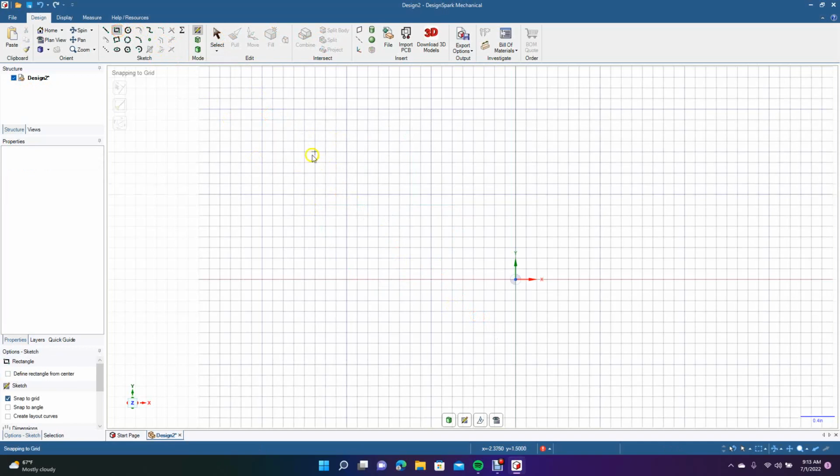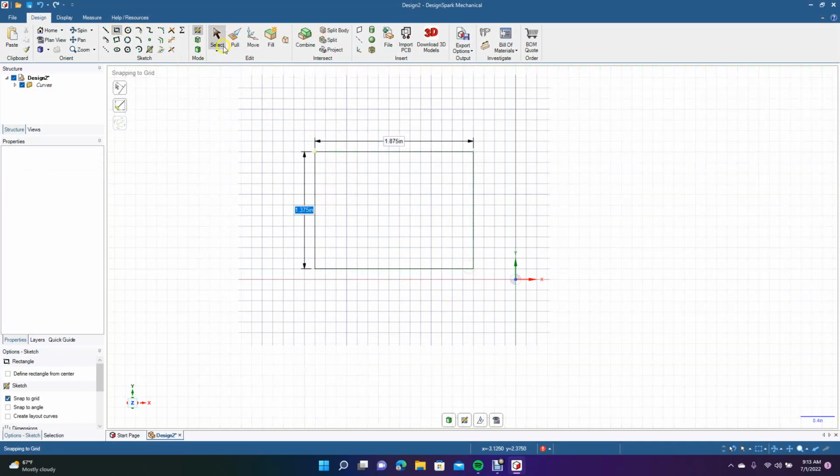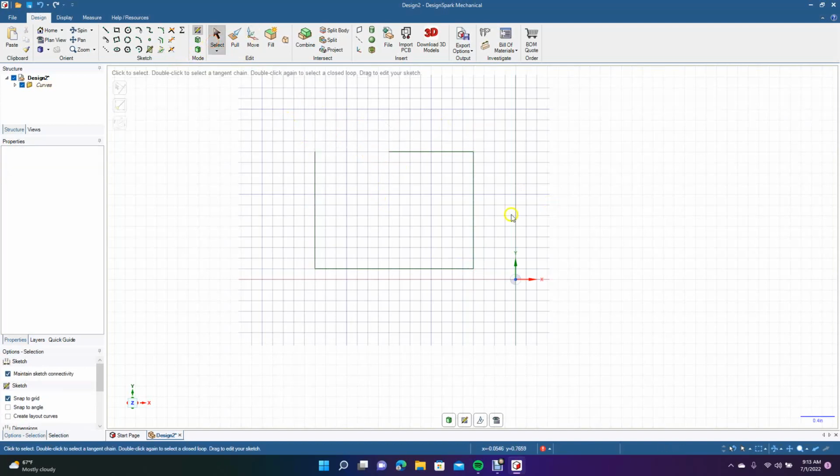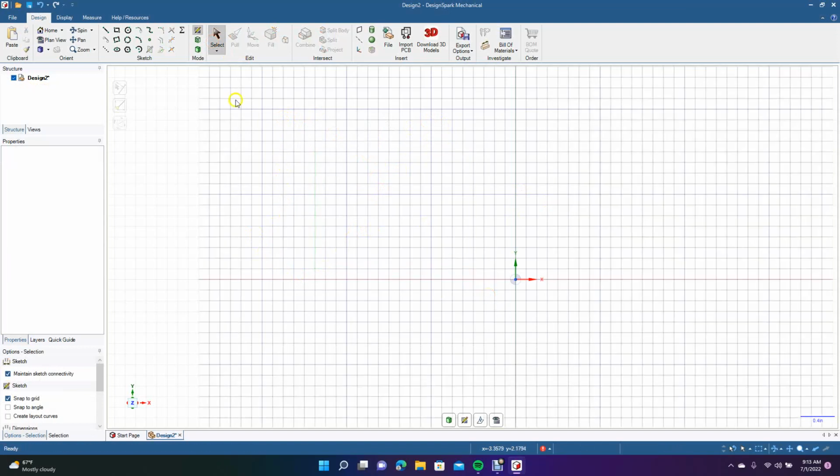We'll go ahead and create a square. So basically if you wanted to create an opening in this, you just draw a couple of little clicks and then you have an open area that you can delete. Okay, so that's going to be that tool. So we'll go ahead and delete. Okay, that's the trim away, the split tool.